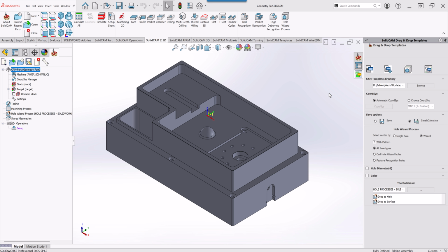In this recording, in our series of creating geometries, we'll talk about chain geometries. And this is the first part of chain geometries. As I had mentioned before, chain geometries is used for creating a boundary to work within it or to work alongside that particular geometry. And our chain geometries in 2.5D are used in profile operations, pocket, chamfer. Those are some of the places that we use the chain geometries.